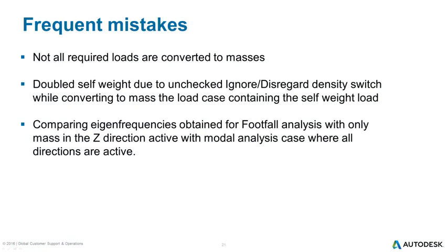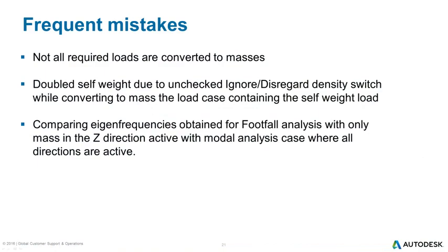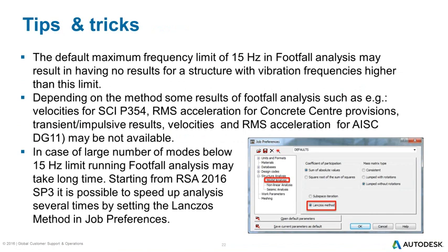The default maximum frequency limit is usually set as 15 Hertz in footfall analysis, and due to this fact, you may have no results if the eigenfrequency of the structure is higher. I'm sorry, it seems that you probably can't see this slide. Okay, yeah, I think that's the correct slide. It may happen that there are no results for footfall analysis as the eigenfrequencies of the structure are higher than the specified limit, which is by default 15 Hertz.